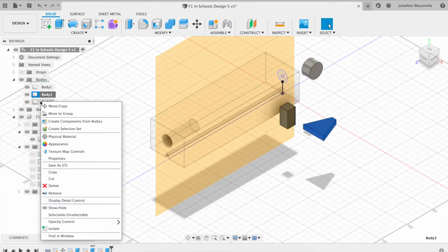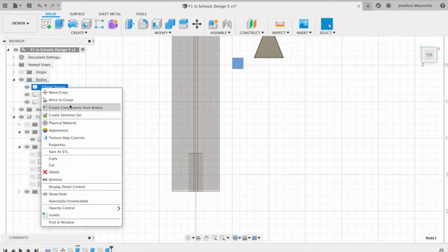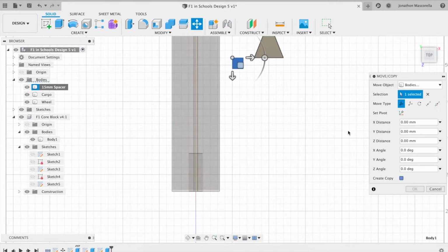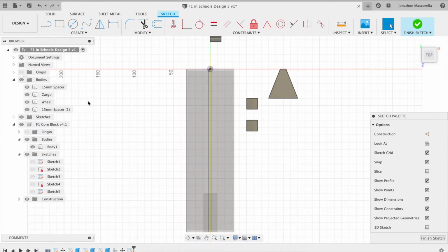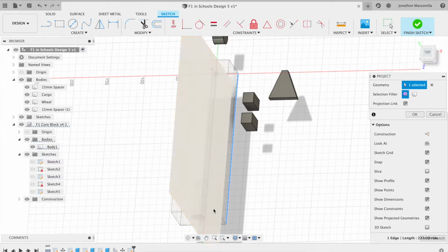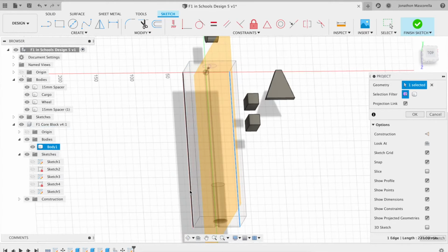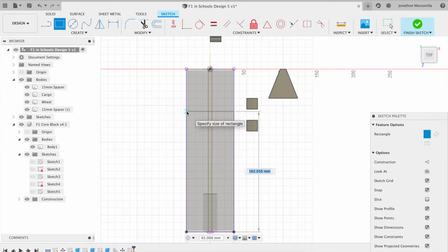Now the main thing here to do is make sure that the places you're going to place them obviously fit within the confines of the maximum lengths or minimum lengths of the vehicle. And the maximum length is 220 millimeters, 223, and the minimum is 170. So in this particular instance, what I end up doing is cutting the car down to 150 millimeters, placing all the blocks, and then using the other 20 millimeters at the front of the vehicle to put the nose cone in, so that the nose cone is placed in the correct place but also extends the front of the vehicle, which means that if it is too short, what we can do is just extend the nose of the vehicle slightly, and that will make sure that we sit within those specifications.